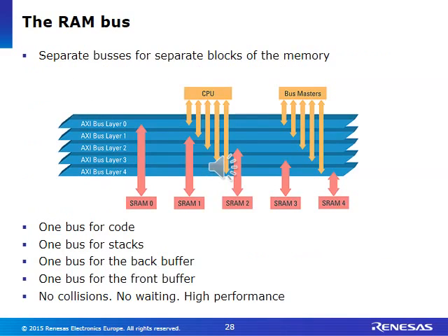In a standard HMI application, there are lots of things happening on the RAM at the same time. First, the picture data is being read from RAM and sent to the screen. Second, the CPU is running its code from RAM. These two things are happening at the same time. Additionally, RAM is being written to by the CPU in order to create that next picture. This means that there are 3 accesses to this external RAM over one bus, happening all at the same time. Wouldn't it be just better and faster if this RAM was internal?